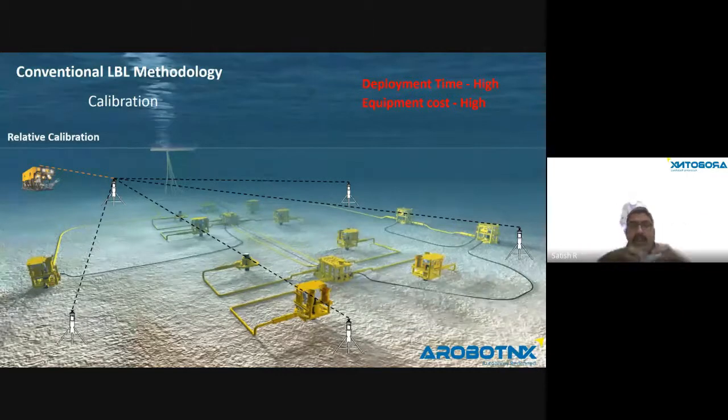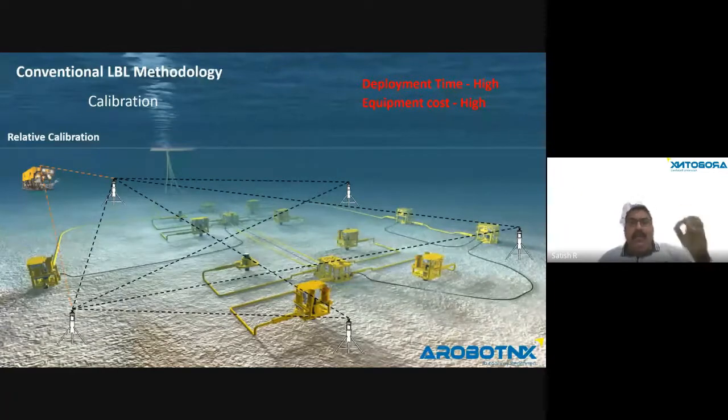So it all jumbles up and calculates, and that methodology is least square adjustment, which we shall not talk about too much today, but you should understand the method. Everything gets adjusted and finally determines the exact position where it is. But you still have to wait for some time, because the final position is derived through adjustments. So the ROV sends this information to each and every transponder, individually asking each one to find out where it is, adjust itself, and just give the final results. So this is how it's happening.